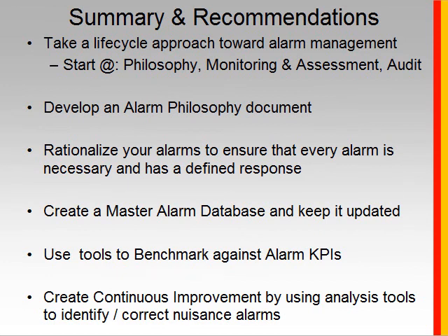So in summary, we've reached the end of our review of the alarm management life cycle. Some of the main recommendations: obviously take a life cycle approach toward alarm management. Depending upon what state the plant or system is in will determine which stage of the life cycle is best to start with.